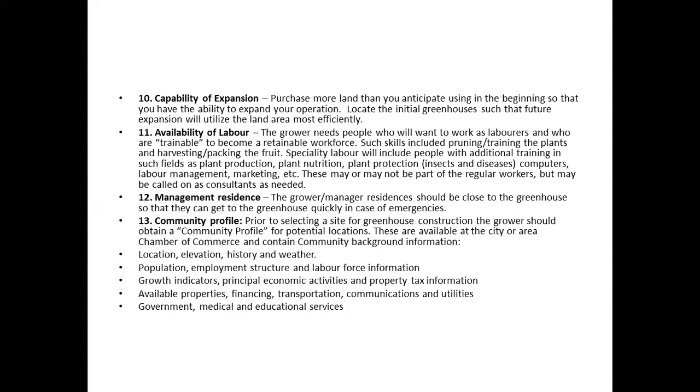Then the greenhouse orientation should be proper such that more sunlight is available and proper ventilation is available, so that naturally ventilated air is obtained for the greenhouse for a long time. Also, a freestanding greenhouse should have its long axis perpendicular to the wind direction so as to keep the greenhouse cool during its sunny timing.